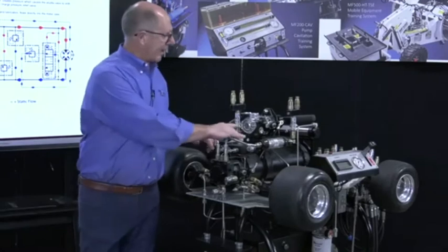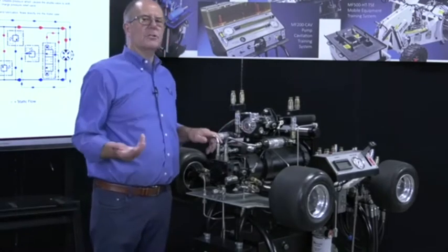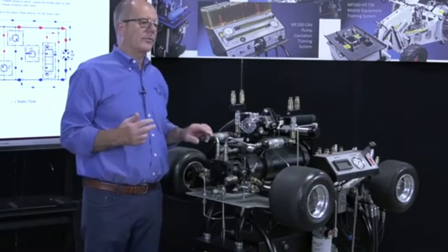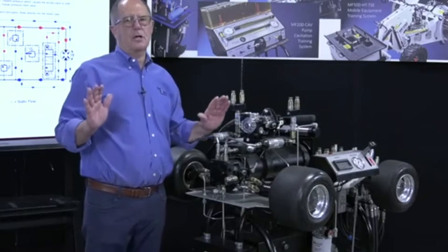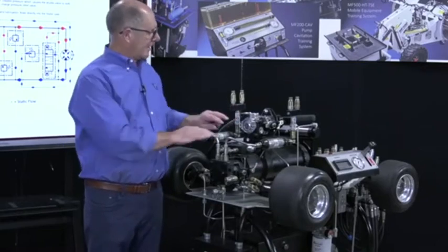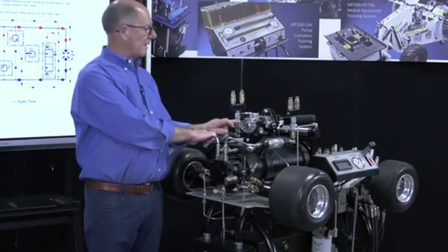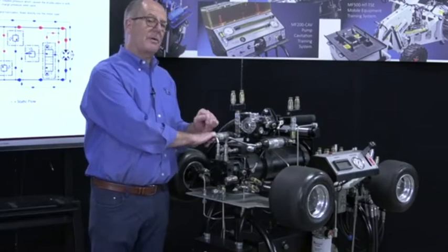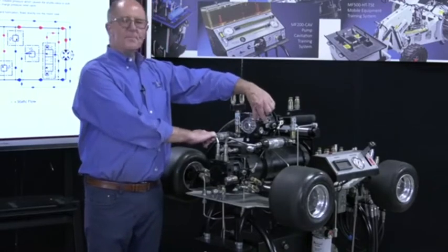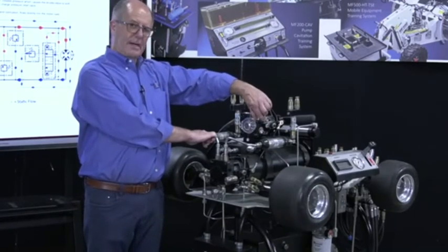It also has a transparent charge pump, which is a Gerotor type, as most are. If you look at any transmission, Denison, Rexroth, Sauer Danfoss, most of the charge pumps are Gerotor, or generated rotor, design. So you've got your charge pump here. You can also see your little charge check valve in here, or charge pressure relief valve. And then on either side, you've got your high pressure valves with your charge check valves.